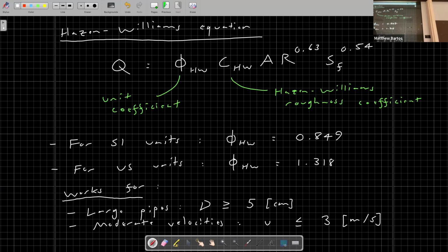The thing is that the largest source of uncertainty will not be the equation itself, but rather how well you can specify the roughness parameter. So really the actual accuracy of the equation itself won't usually matter as much as long as you can get the roughness established. And roughness is something that's very difficult to measure directly, so that's often very difficult to do in practice. Okay, good question.